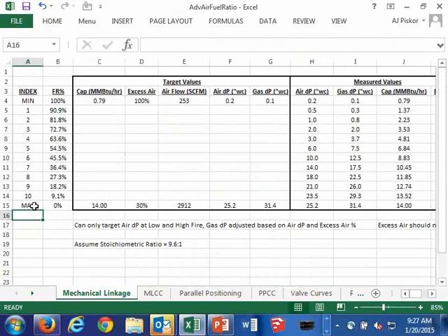So a Maxon mechanically linked microratio valve, it's got a screw carrier assembly that allows you to fine-tune your gas. So there's essentially 12 different index points if we look at column A. And you'll see that there'll be tick marks next to the screws on the screw carrier assembly that indicate minimum fire, and then there's index 1 through 10 going up to maximum.